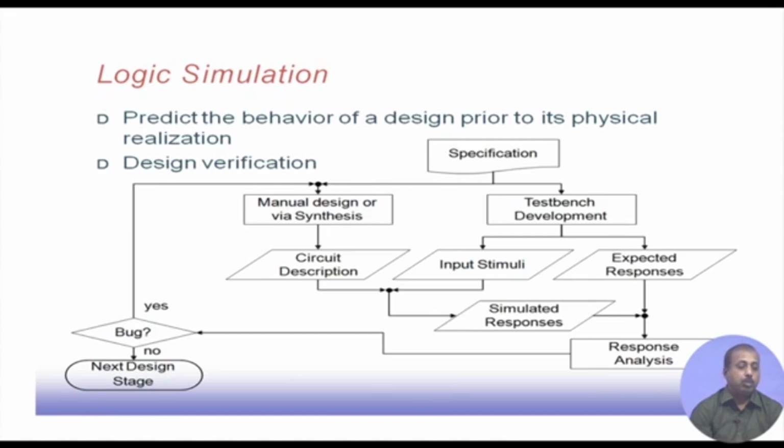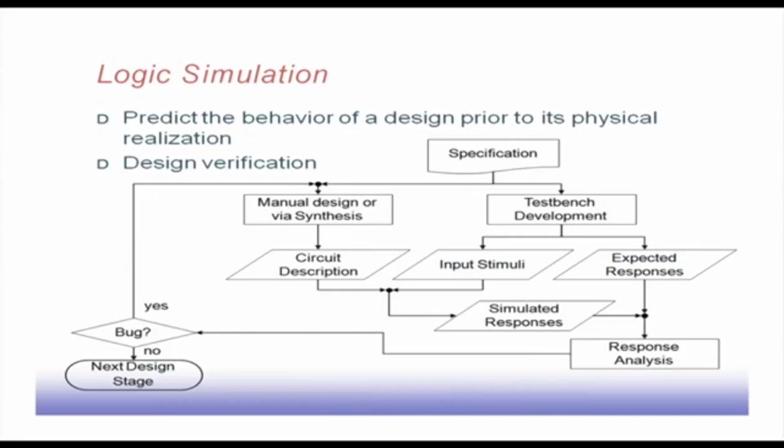But what about the quality of the test bench that we have developed? With respect to a given test bench, we are getting the confidence that there is no bug in the system, but it is actually only that the system does not contain any bug which could have been detected by this particular test bench. Only this much is the confidence level. So, to have a better confidence, the test bench development should also be judged, like how good or bad this test bench is.